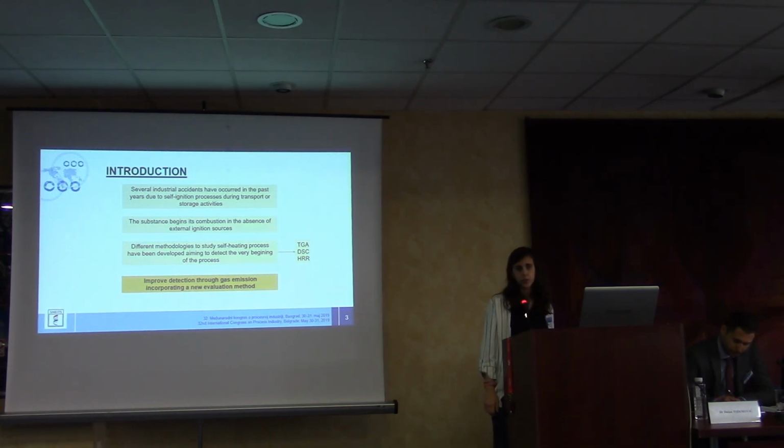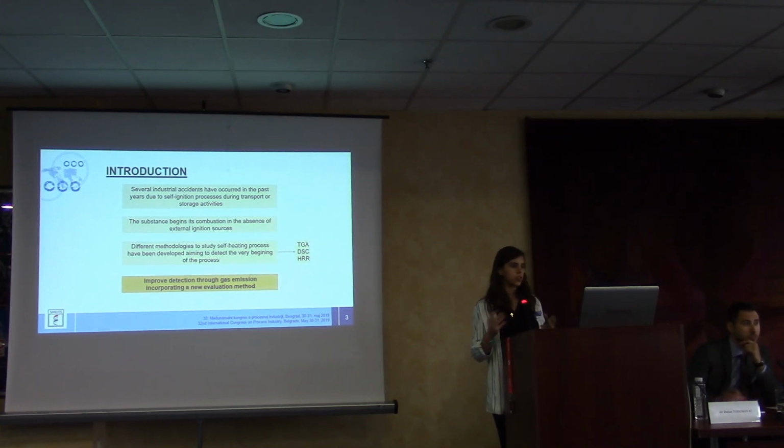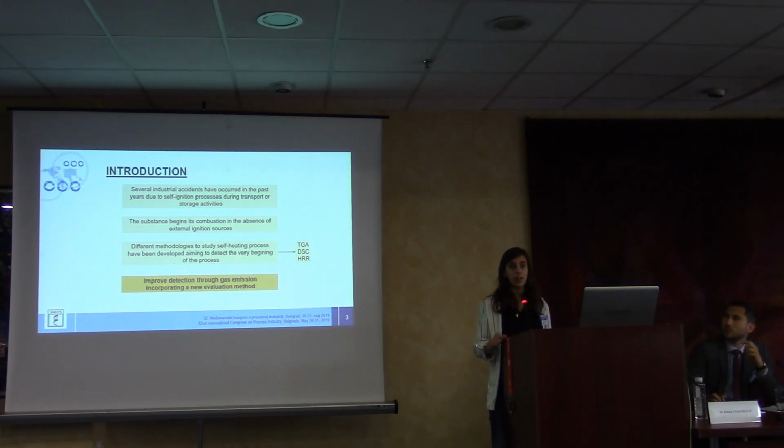Different methodologies have been used in the past years to study the self-heating process, as for example TGA, thermogravimetrical analysis, DSC, differential scanning calorimetry, HRR, heat release rate. But I'm going to use a different, not so common methodology, which is through gas emission, gas related to combustion emission. Why? Because it's really cheap, and if we can make it work properly, we could use this methodology to detect those processes without wasting money in really expensive equipment.